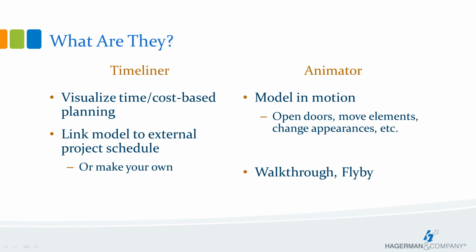Now, the Animator tool links object and viewpoint behaviors to your construction schedules, and that can enhance the quality of your simulations. For instance, you can start your simulation with a camera showing an overview of the whole project, and then as the tasks are simulated, zoom into specific areas for a detailed view. You can also play animation scenes as the tasks are simulated, which is nice.